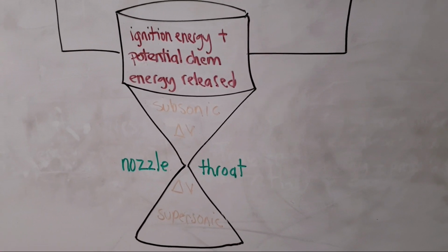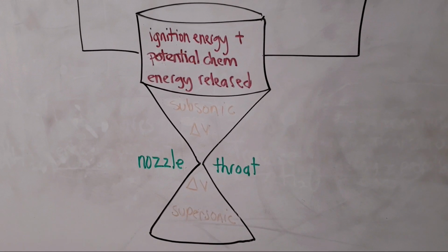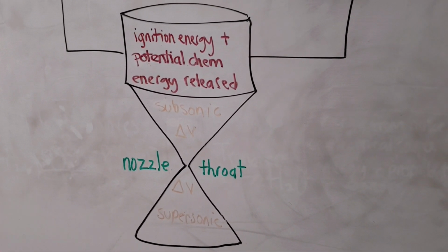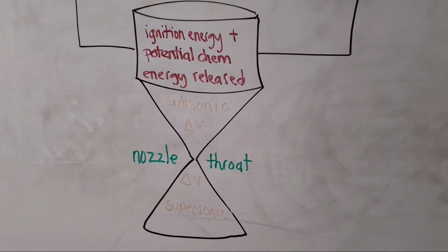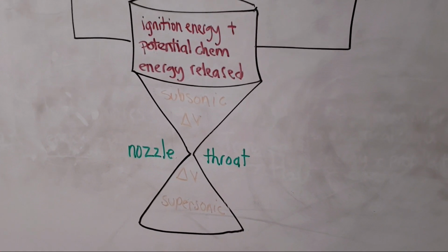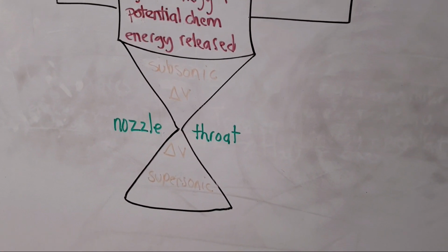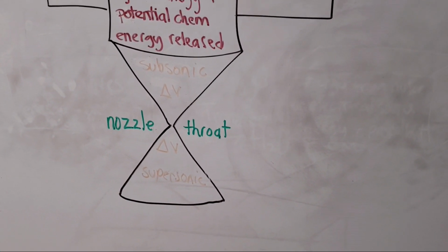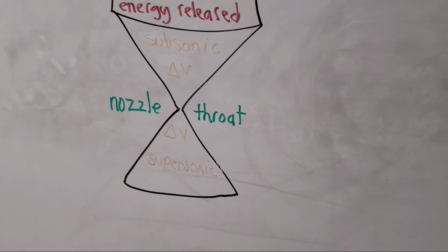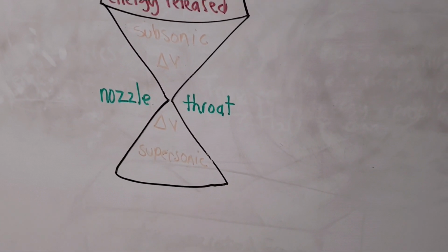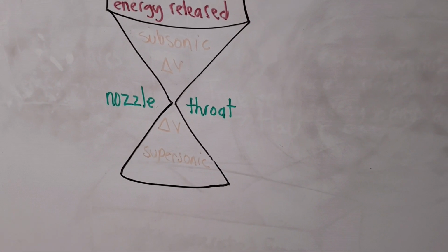So one thing I really thought was cool was when we moved down to this converging rocket nozzle. An important phenomenon in fluid flow, and I thought this was really interesting, is that subsonic fluids will always accelerate in a converging nozzle until they reach the speed of sound, or Mach 1, at the nozzle throat. And then something even more interesting happens here. Above the speed of sound, as these fluids are flowing at supersonic speeds, they will again continue accelerating through supersonic velocities out of the diverging nozzle.